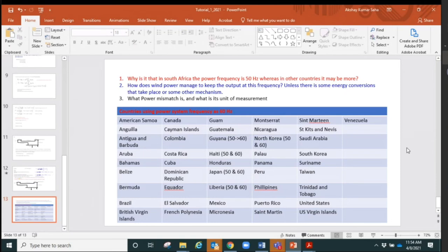I do other corrections, and if after 10 or 20 iterations it's still saying 45 and 32, then I control the generators at the swing bus to change the megawatt from 50 to 45 and the megavar from 40 to 32, because that's the mismatch. Okay, I understand, sir. Thank you. And when we control the generators such that the megawatt becomes 45 and the megavar becomes 32, the mismatch is now zero, so the system is steady.